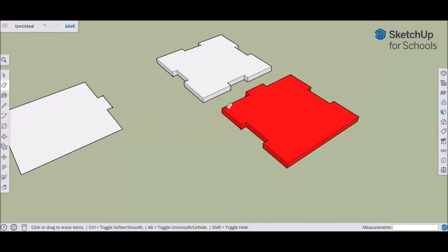Now here I need to take away these pieces, which is 25 from that point to that point. So ruler, take measure of it. I go from there, measure along, I'll get to 25, click. And I go from there, from that guide point to this edge, click on 25.5. Take measure. I'll get from that point down 25. Click. Give me a nice long line across the whole thing, which is